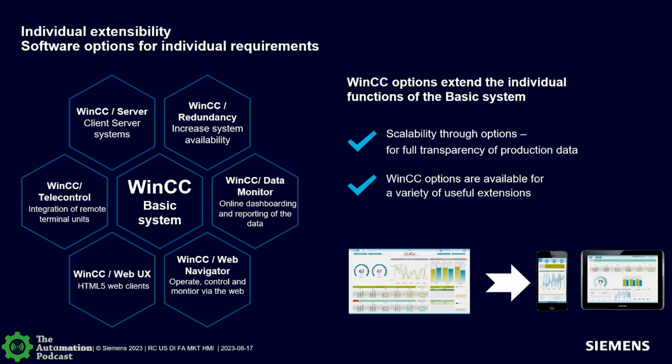So that's where we started making that shift about 3 versions ago, and had to do a lot of development work because with Web Navigator, we're using a lot of Microsoft ActiveX controls, which didn't work in HTML5. So we redeveloped a lot of our controls and a lot of other stuff to give us those Web UX and HTML5 capabilities. The pictures here just show where you could have your WinCC screen, and, oh, I need to display information on a cell phone or an iPad. I could create screens for that and pull the information in.